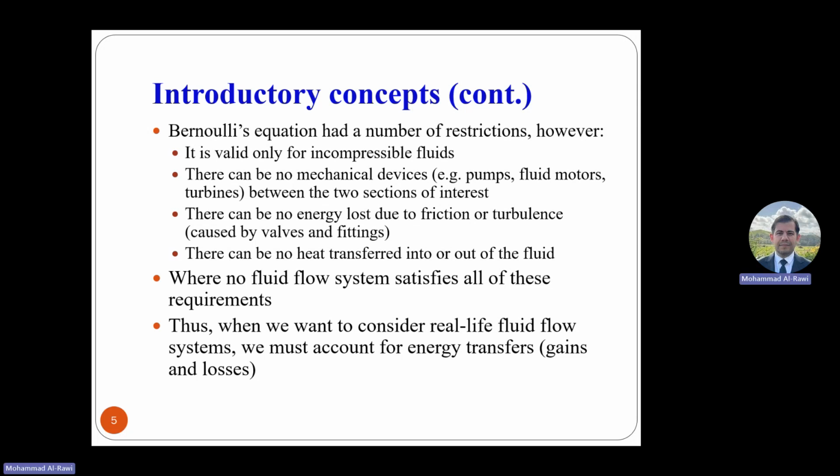And there can be no heat transfer into or out of the fluid. When no fluid flow system satisfies all of these requirements, you need to use the general energy equation for real-life fluids, because it will take into account the energy transfers, which could be gains and losses through the system.